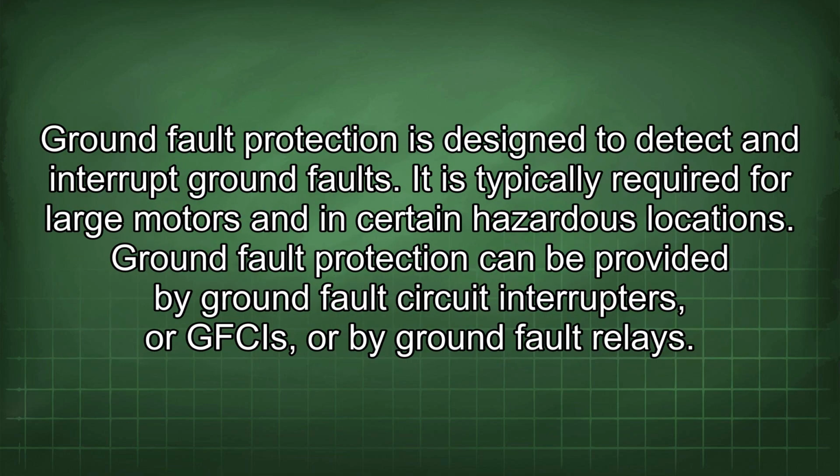Ground fault protection is designed to detect and interrupt ground faults. It is typically required for large motors and in certain hazardous locations. Ground fault protection can be provided by ground fault circuit interrupters, or GFCIs, or by ground fault relays.